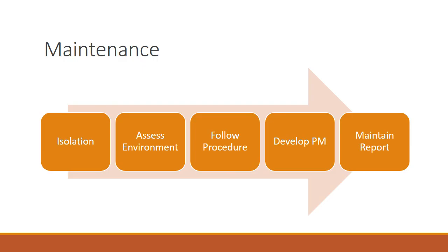You should check the instruction manuals that came with your switchgear to determine if there are any specified replacement schedules that are dependent on the usage and the age of the switchgear.